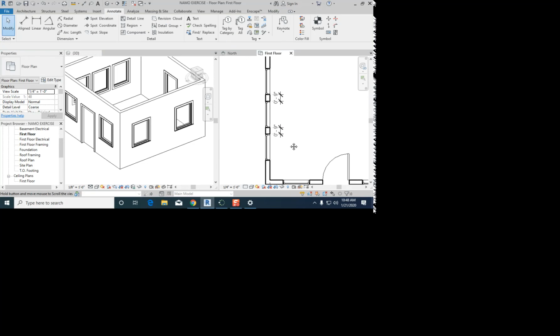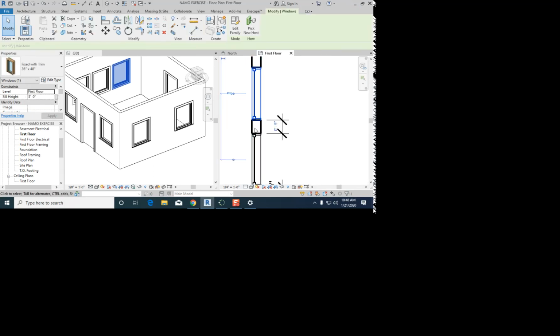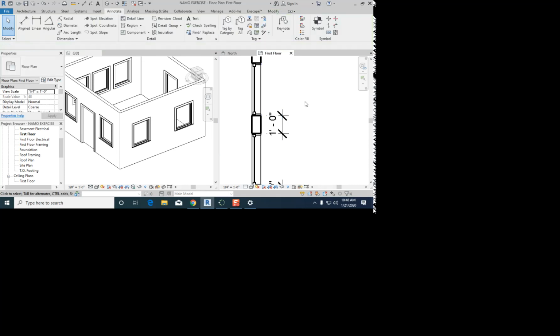Okay, great. So I'm going to use the example I did to Olivia, right? So we're Vanna White, and to move something, you have to click on it first. I want to move this window, and I want this window to be how far from this window here? Do you remember the distance? A foot. So I click on where it says 9 inches, and I'm going to tell Revit, move this 1 foot away, and it should be a foot away.